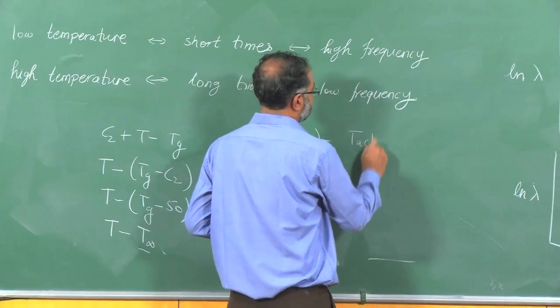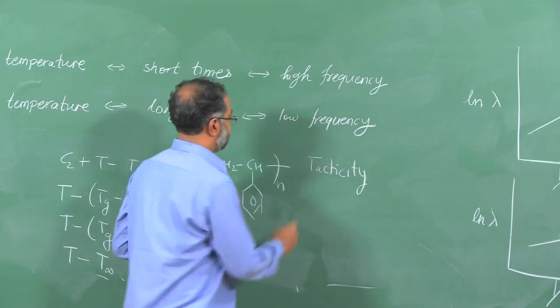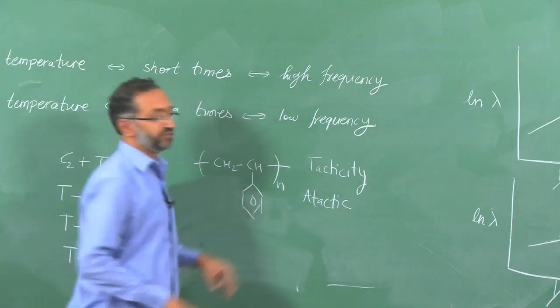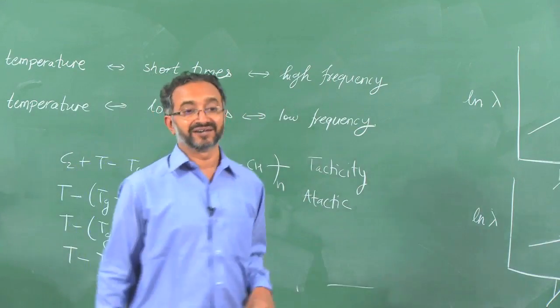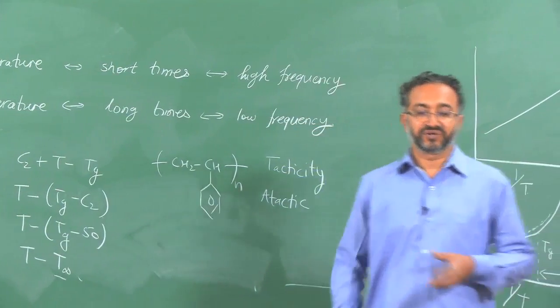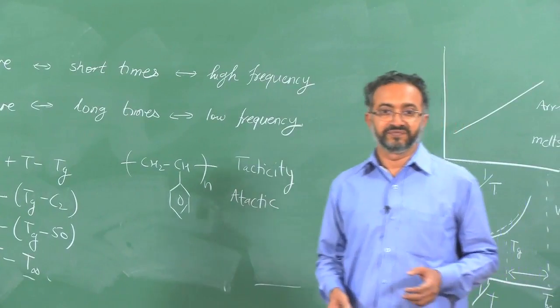So generally this material is atactic, which means how this bulky group is distributed is completely random. In that case you will never be able to crystallize that material, because a crystal cannot be formed since a regular arrangement is not feasible.